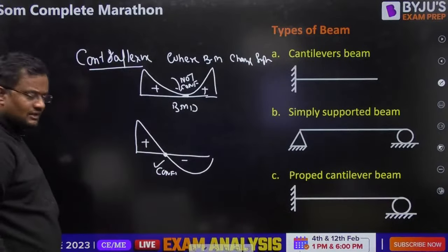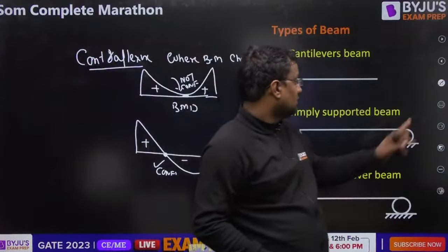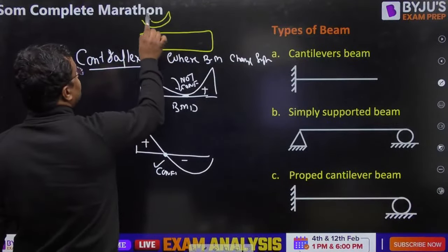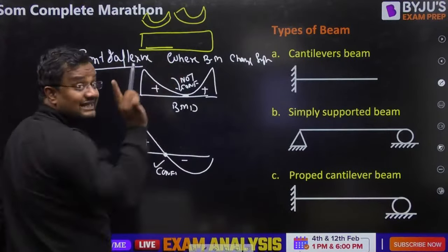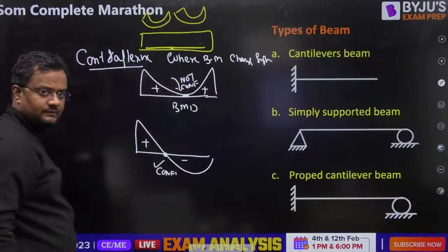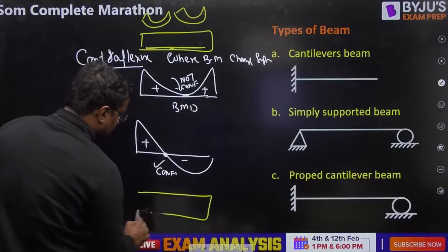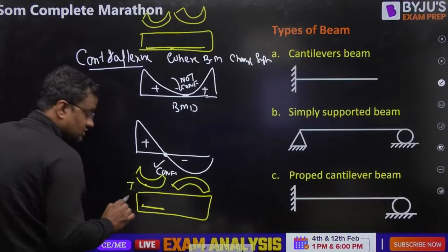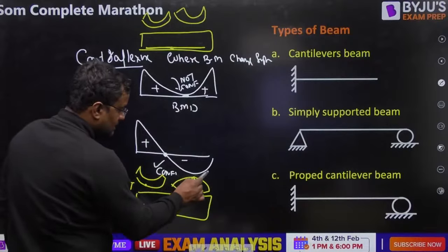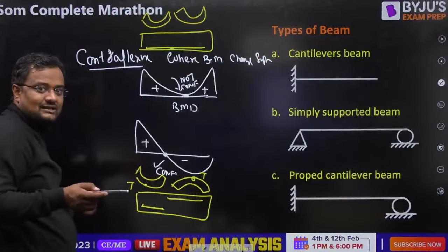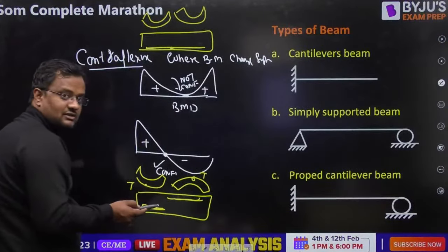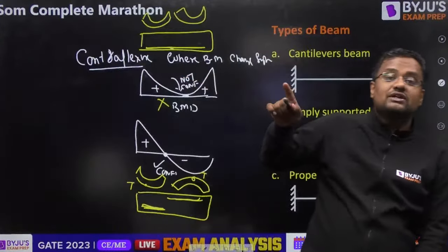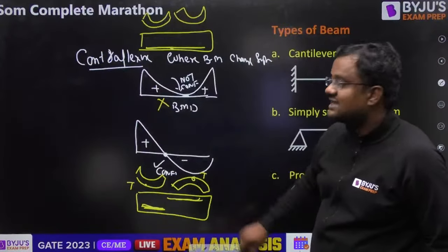Why? Let me tell you. Suppose a beam is like this. Positive bending moment means sagging, so the deflected shape is something like this. Because concrete is weak in tension, tension steel will be at the bottom only. Negative means hogging, so here the steel is at the top because tension is there. So contraflexure represents where the direction of tension reinforcement changes. That is why the correct definition is not where bending moment is 0, but where bending moment changes sign, that is contraflexure.